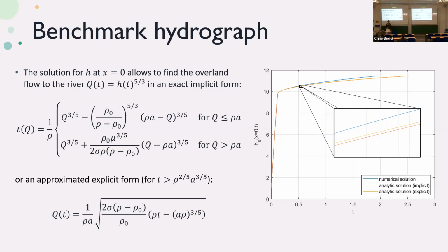And now, since we have this benchmark hydrograph, we can compare whether other models than our physical model, like data-based models based on this dynamic system or statistical models, will predict similar behavior of the system, similar scaling laws, by describing Q as a function of all the catchment parameters that you can see here.